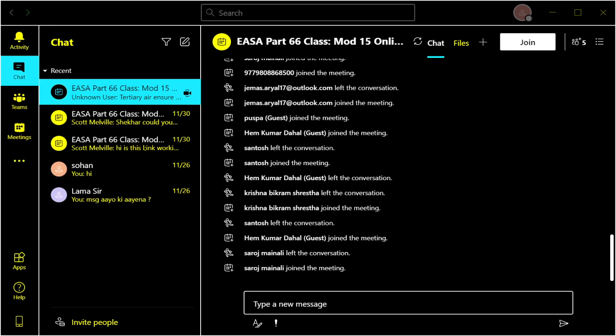It's a thread type where you screw it into the housing just before the bearing. There's your oil feed as it goes through this very fine mesh, and so that's the last chance, hence the last chance filter, just in case there's a small amount of debris that might have gotten past for whatever reason. And the last thing you want is even the smallest grain of dirt on a high-speed bearing, as it's going to cause a bit of damage. So this little filter can prevent that from happening. Okay, so that's your main sort of filters there.